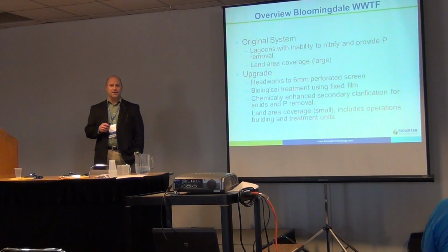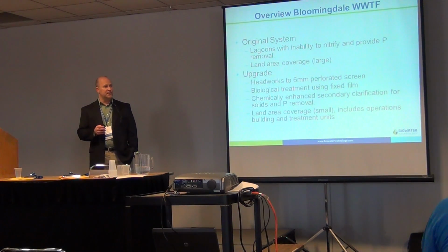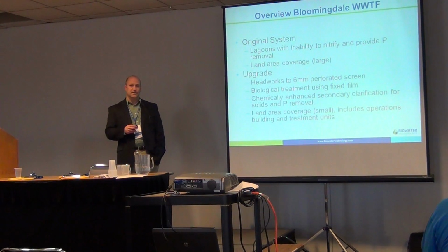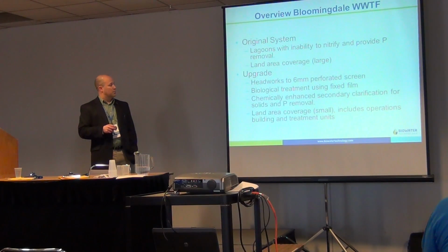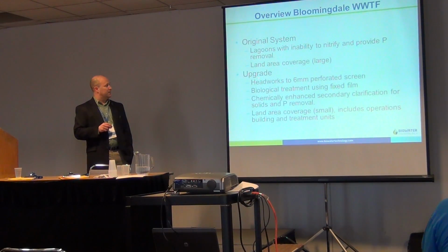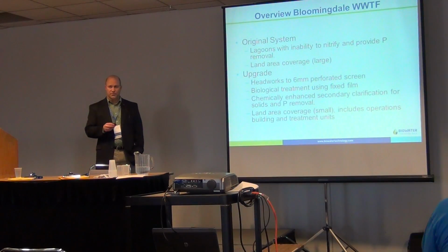Lagoon systems can do a great job at BOD removal, but without that additional aeration, they really can't get to a nitrification step. And they'll take up as much phosphorus as they can, but they really aren't proficient at that either. So what we were charged with in the upgrade was to build a new plant that wasn't a lagoon plant, a mechanical plant.